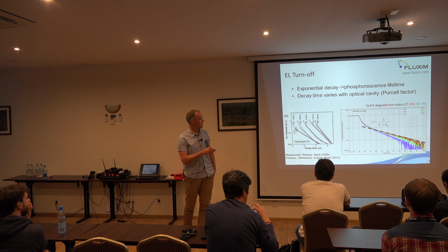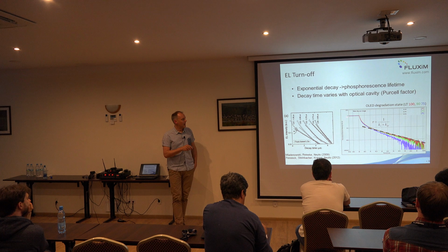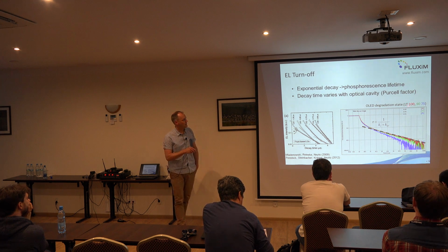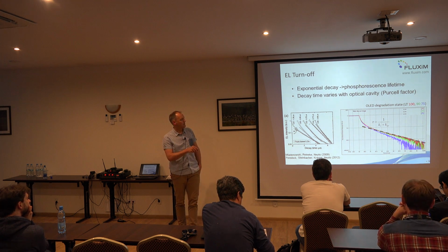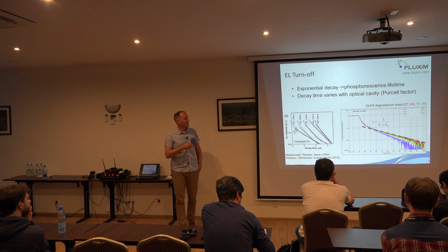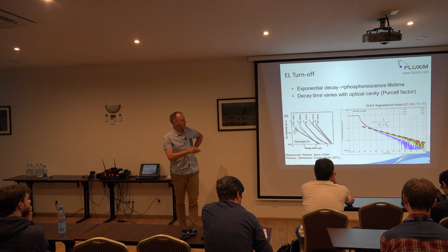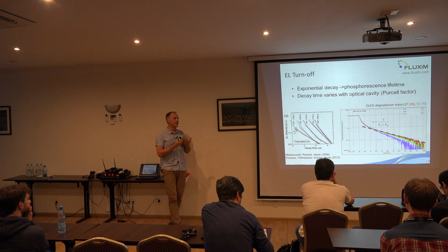And here we also have this OLED degradation study, where the fresh OLED, 100% light output, had a certain decay here in log intensity. So it's not really mono-exponential, but interestingly, for the degraded OLED, only 75% light intensity, the decay was faster. So what it means in the degraded OLED, there was an additional decay channel, maybe non-radiative decay of species.